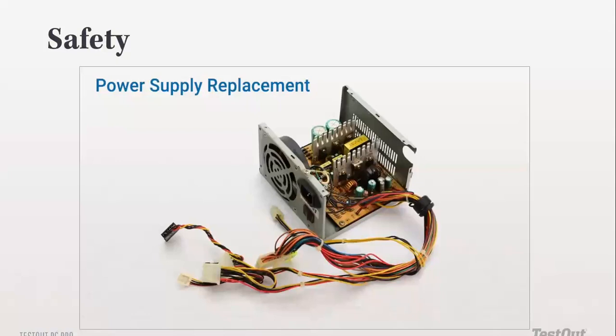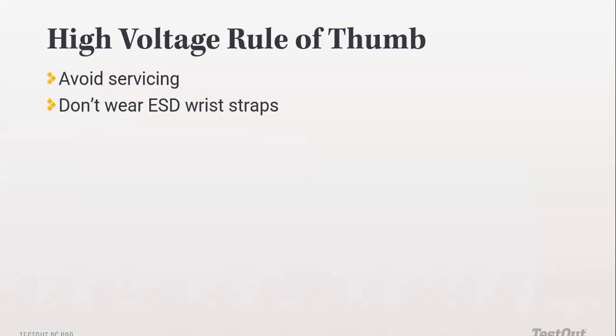So you know that the human body conducts electricity. If you try doing maintenance on this particular component, the electricity in it is enough to kill you. There is enough electricity stored in these capacitors to kill an adult human being. So all in all, do not maintain this component and rather replace it.